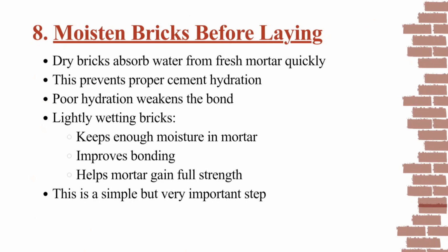Now rule number 8. Moisten the bricks before laying. Dry bricks absorb the water from the mortar quickly, which prevents the proper hydration of the cement. And that's why it weakens the bond between the bricks and the mortar.